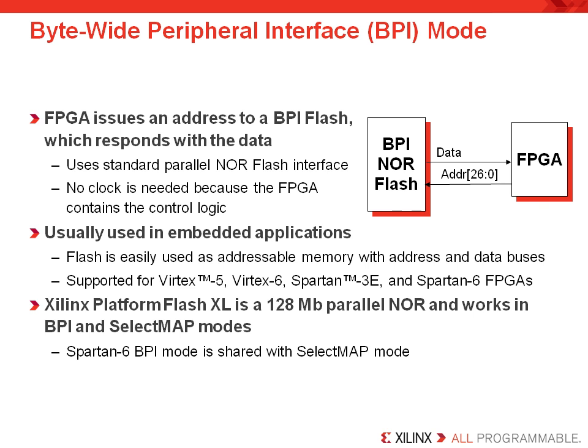The other version, called BPI Down, starts configuring the FPGA from the highest memory location and automatically decrements the memory addresses. This addressing flexibility allows the FPGA to share the parallel flash PROM with an external or embedded processor. Depending on the specific processor architecture, the processor will boot either from the top or bottom of the memory location. This allows the user to maximize the use of their flash device by allowing the software code to be stored in the same flash device as the bitstream. Note that BPI Down is not supported for Spartan 6 devices.